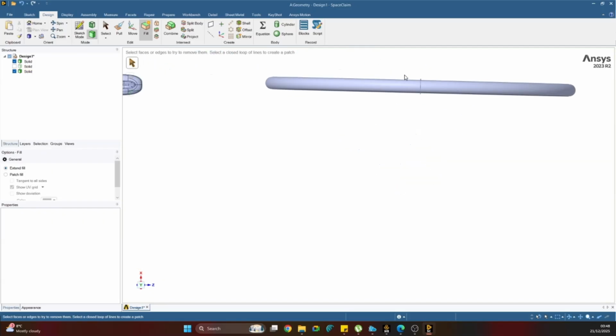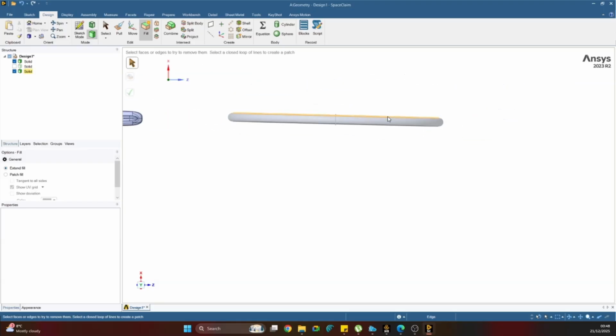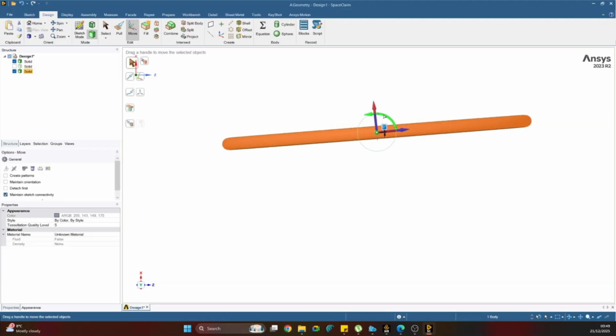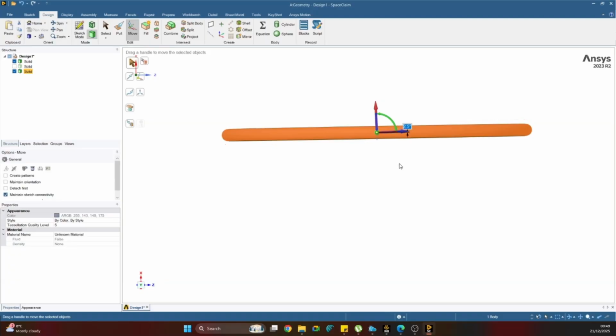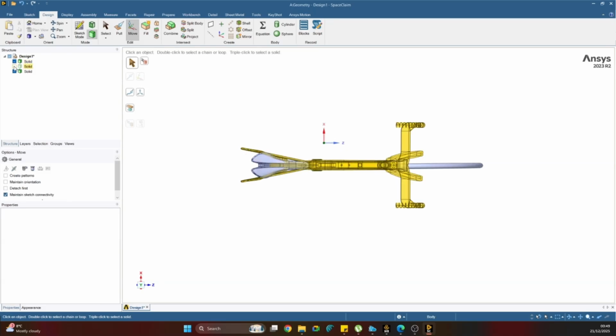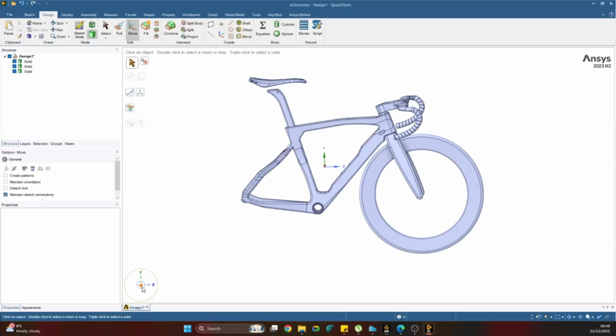And now you can see our tire is tilted. It's not in a straight line. This is because the geometry that was provided was not appropriate. This is why it is happening. So we will try to rotate this wheel by 3 degrees. So you just have to click on this tire and then click on move and then rotate it by 2.5 degrees and we will see, okay, it is approximately straight. Let's try 2. 2 is, I think, perfect. So 2 looks decent.